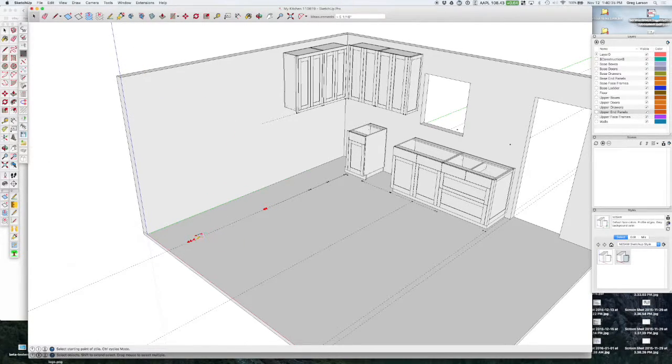And now I'm going to use my distance tool again, Control, and if, let's say I'm going to make two cabinets here, a two box cabinet, I want to go over, let's say 30 inches to fit an oven. So I'm going to click here, go over 30 inches, typed in 30, and go back on the line, and that's my connector style.